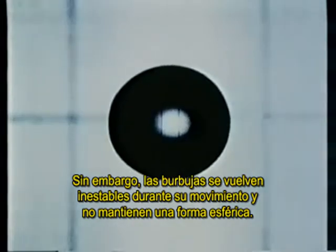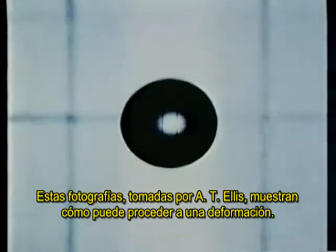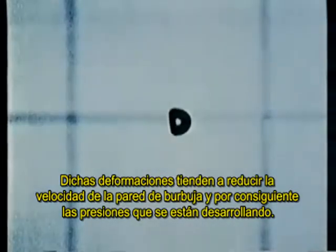However, the bubbles become unstable during their motion and do not maintain a spherical shape. These photographs, taken by A.T. Ellis, show how distortion may proceed. Such deformations tend to reduce the velocity of the bubble wall and consequently the pressures that are developed.